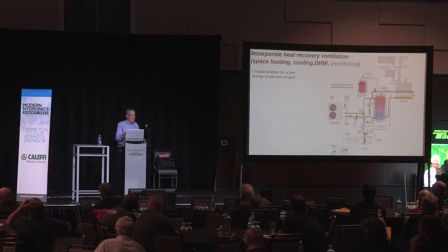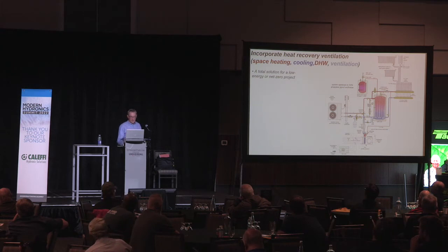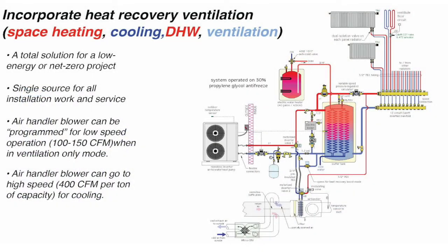Why not take another circuit from, I'll see if I can trace it here, from right here. This could be a piece of 1/2-inch PEX, goes into the diverter valve, and what this is doing is it's going to allow some warm water to go through that coil as a ventilation air booster. So instead of 46-degree air coming out, we could bring that air up to, let's say, a room neutral temperature of 70 degrees. And the way that is being regulated is just a thermostatic valve.